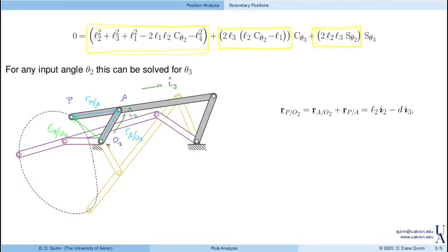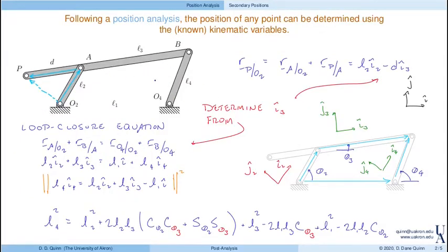So, how do we express this final outcome? Well, we make use of our direction transformations. So I2 is cosine of theta 2 in the i direction, plus sine of theta 2 in the j direction. I3 is cosine of theta 3 in the i direction, plus sine of theta 3 in the j direction. And again, this is how we defined I2 and I3.